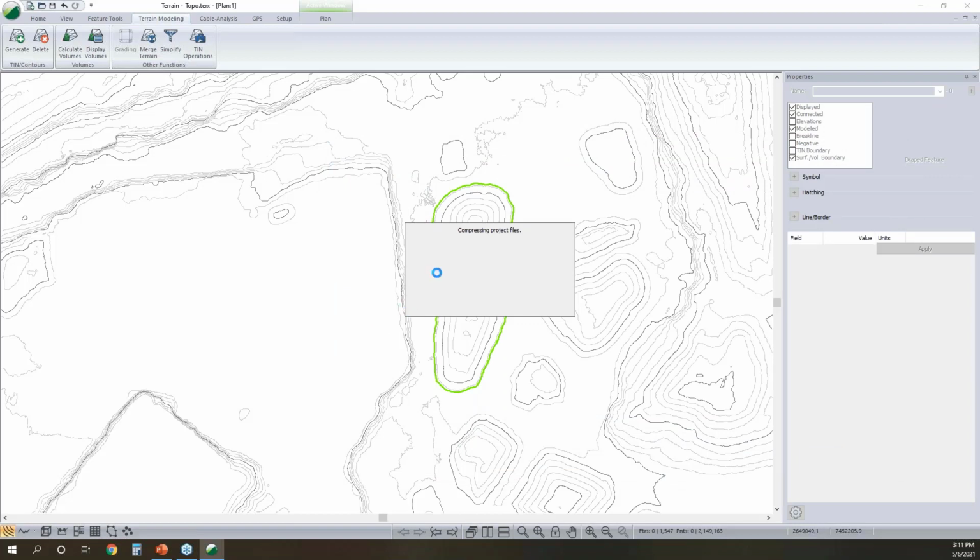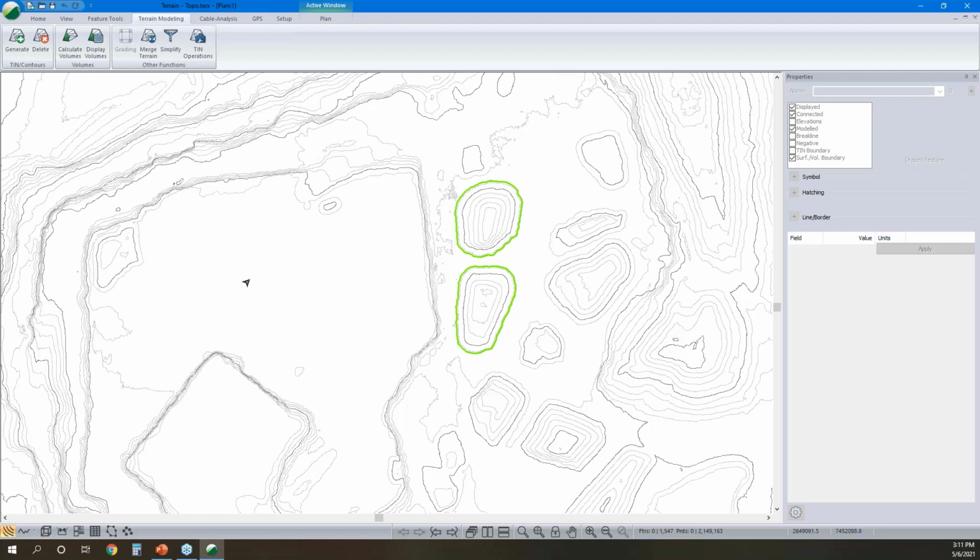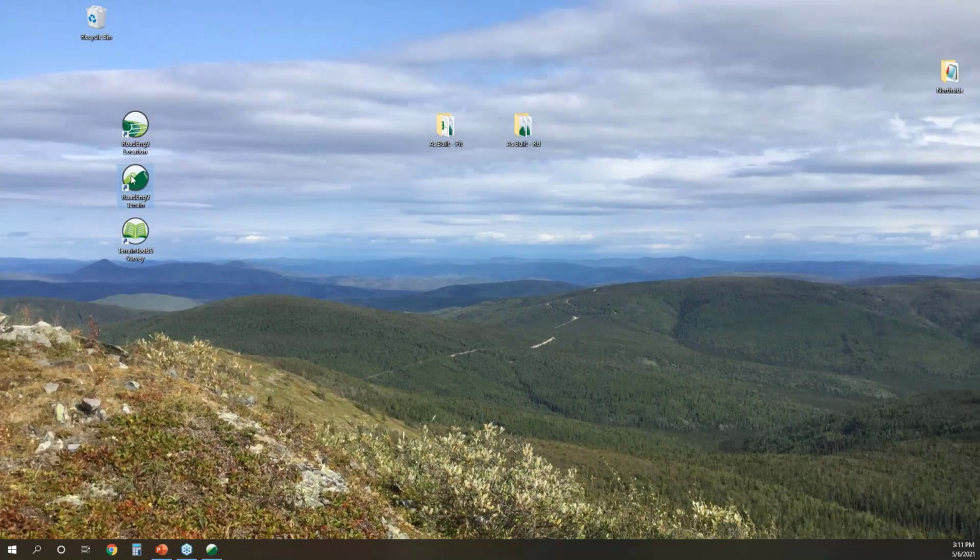Let's run through a different scenario where we've got, say, LiDAR data that was shot a while ago, and we want to keep track of our progress opening up this pit. We've extended out the excavation for the pit floor here, and we've surveyed it, and let's compare those two surfaces. So for that, I'm going to open up another instance of terrain.